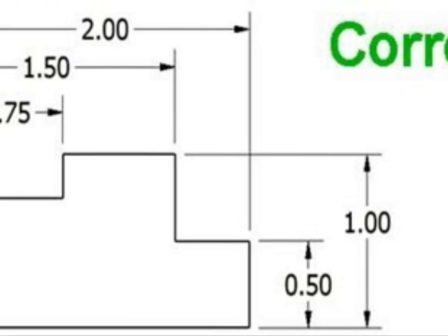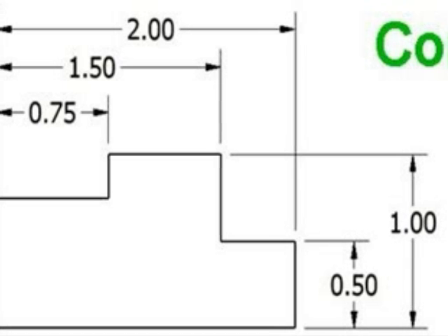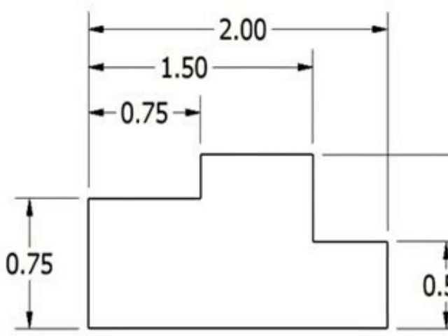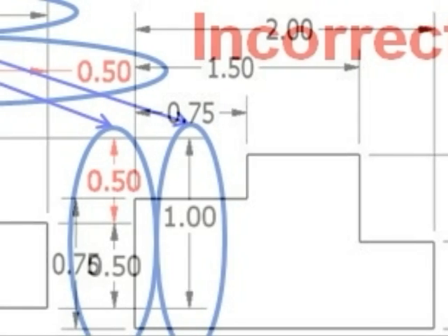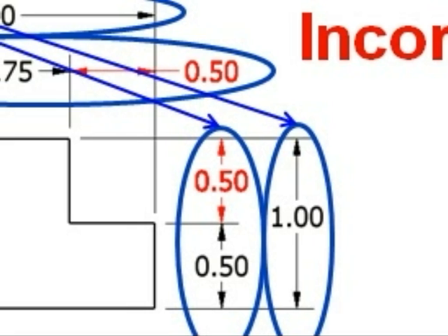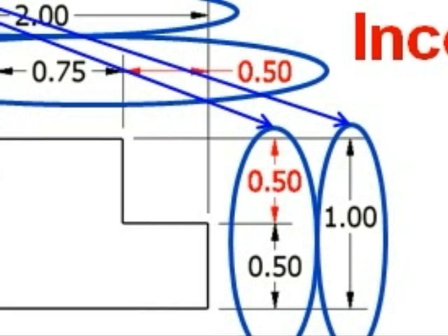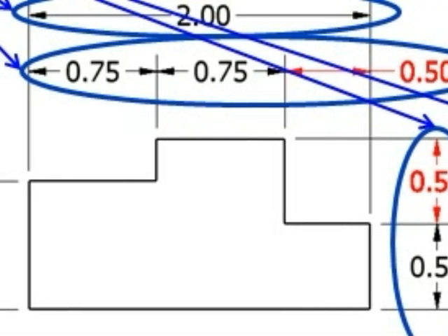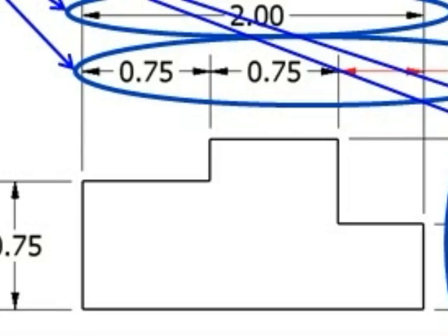With this drawing, the dimensions are dimensioned correctly. No dimensions are repeated, no dimensions overlap, and each dimension that is needed is listed. This drawing is not dimensioned correctly. As seen with the width and height dimensions in the front view, one of the dimensions is unnecessary in each chain and should be removed. Overall dimensions for width, height, and depth must be present.